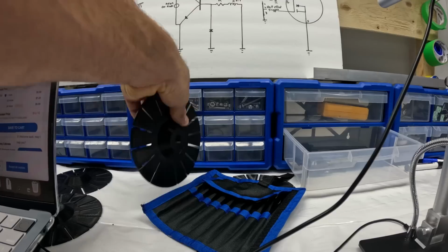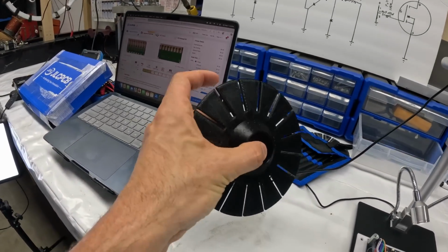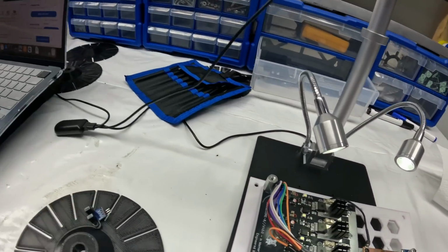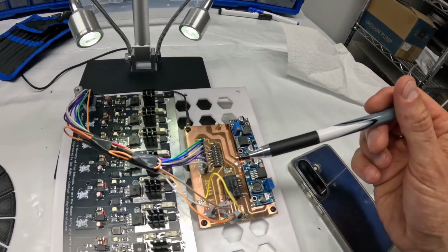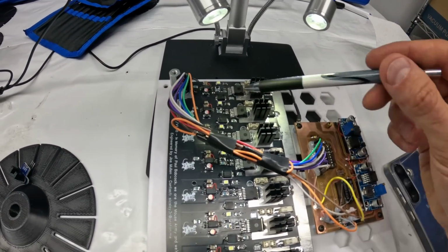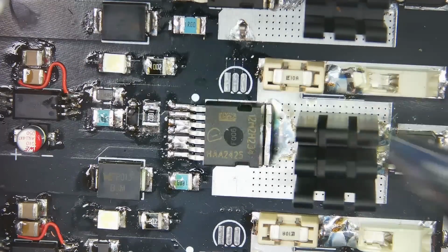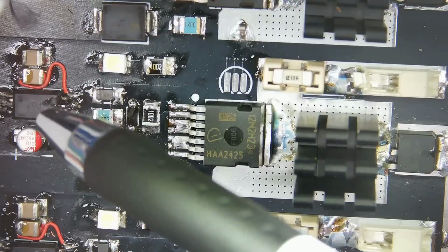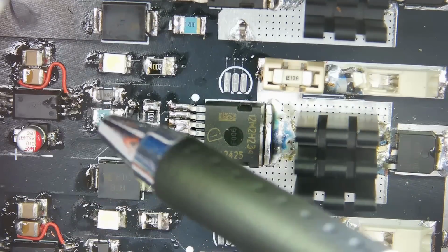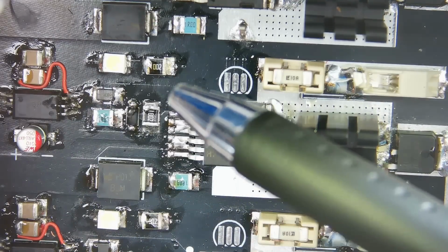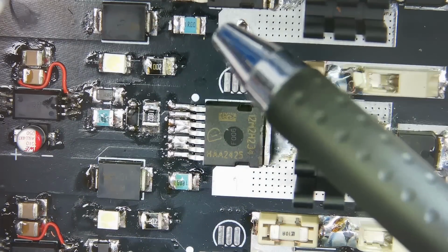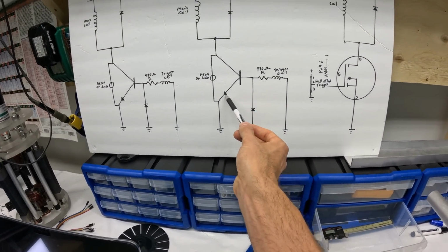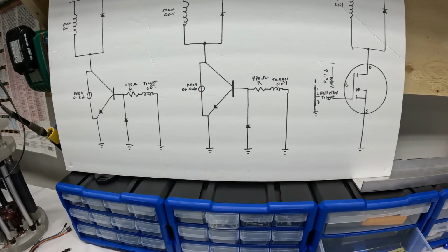So we're using these timing wheels to trigger these optic sensors here, and then that signal is being fed from this board into this driver down here, the one with the capacitors across it. The caps are just cleaning up the electric noise, and then we go across into this N-channel MOSFET. Same thing as this part here. The N-channel MOSFET is just replacing this BJT transistor.